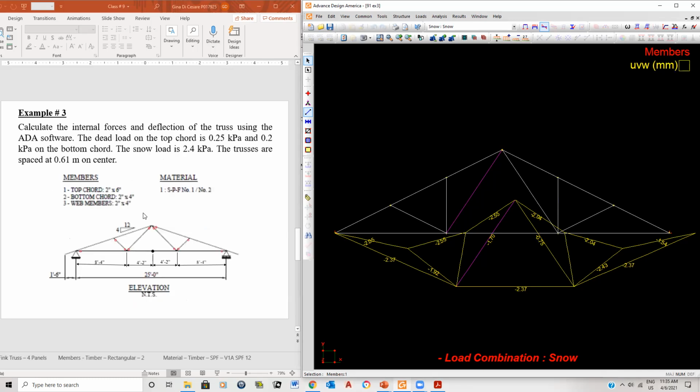So here I'm going to show you, for example, this is a real wooden truss. In the wooden truss, this member here is continuous. This member here is continuous. This member here is continuous from here to here, but it's pinned there, continuous there, pinned there, and all the wood members are pinned. So this is really how you would have to model a real wooden truss. And of course here, it's got a span of 25 feet. It's got an overhang of 1.2 feet and so on and so on.